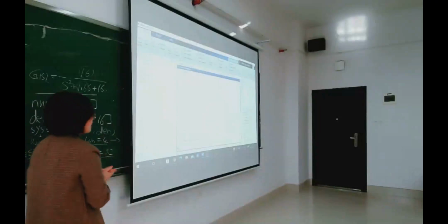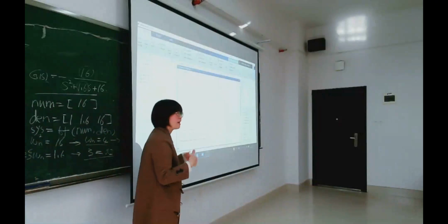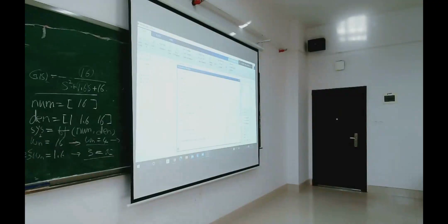And the transfer function is showing here, the simple one, right? Then how to get omega n and zeta by code, not by hand? From this we can read omega n squared is 16, and by this we can read zeta is 0.2. Then there is actually a code to help us get omega n and zeta. What is the code?